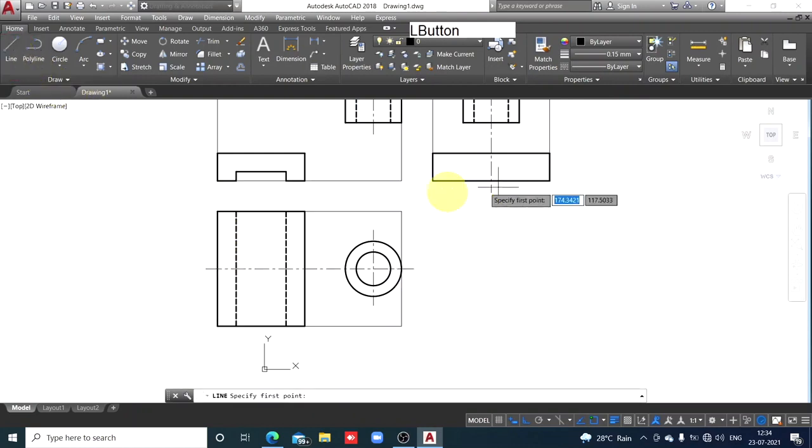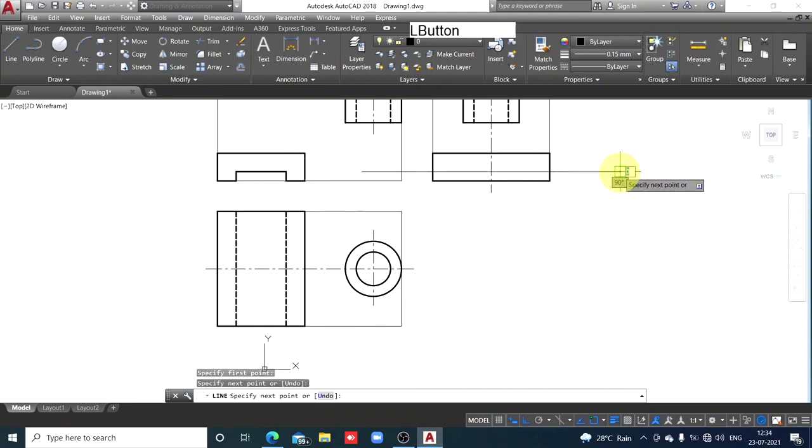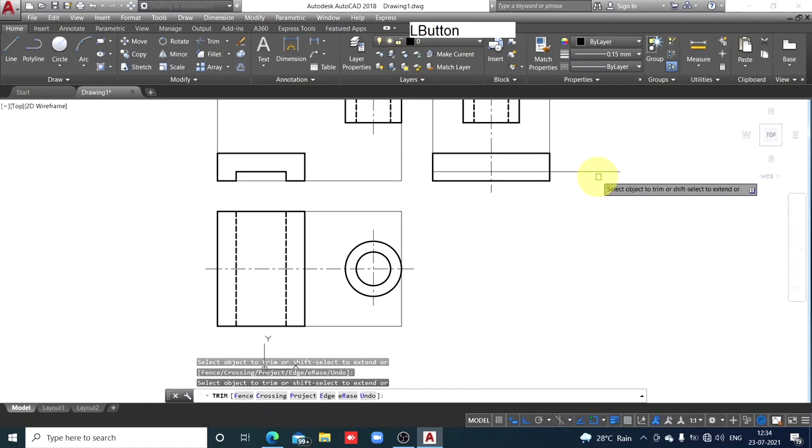Similarly, the same slot on the right side. Check here, 4 corners of the opening of the slot. From these 4 corners there must be edges parallel to width. Listen, this is a corner, with an edge parallel to height and parallel to length. These 2 edges you can see in the front view. Now the edge parallel to width is to be shown in the side view also. This is the parallel to width edge in the top view, a dotted edge here. Similarly a dotted edge here. So line we have selected, now simply track that. Trim, enter. Match properties.